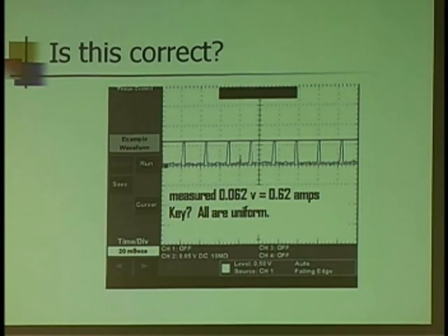Go down. So could I set my trigger to trigger on the down slope or set it for a trigger level at that current level and then just let it run? And when it starts to draw a trace, I'm going to see that problem. Or vice versa, I can set it for above normal.